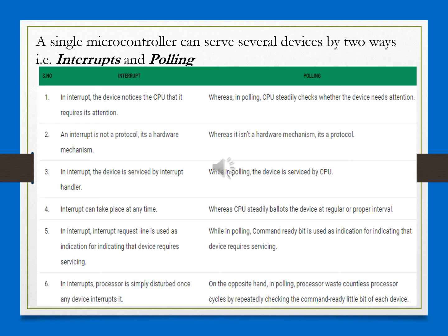So that is a situation like polling. I had used this term earlier also. In this polling method, the CPU is unnecessarily tied up, wasting time and machine cycles, waiting for a particular device to know whether it requires a service or not. So this can be overcome by the interrupt method.